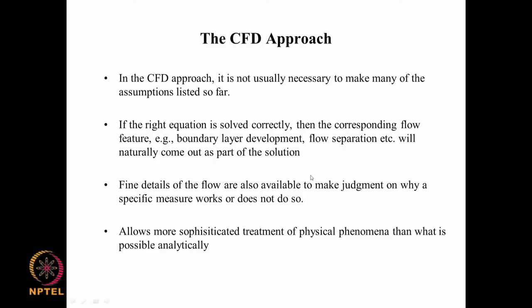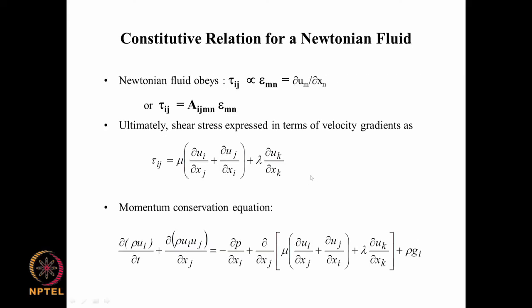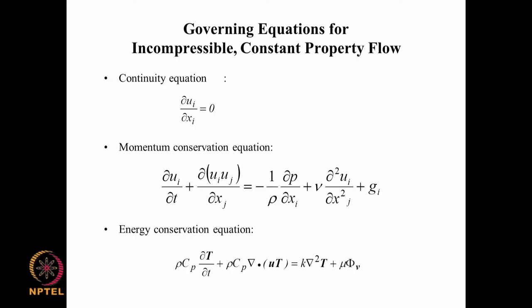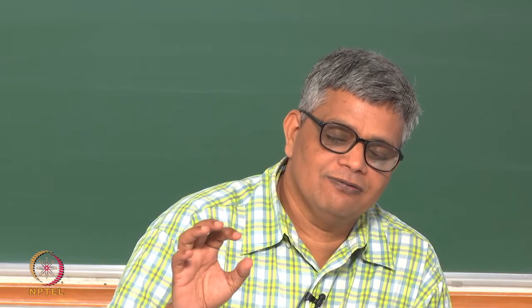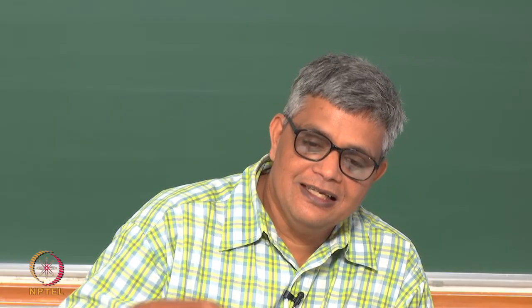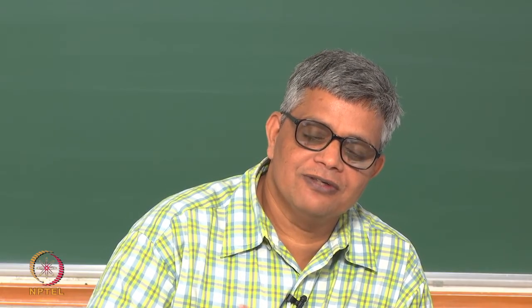In the general case, we have only the Navier-Stokes equations that are applicable, and these are the things that we try to solve, so that when we solve any CFD problem, we do not make any assumptions as to whether the flow is creeping flow, whether it is boundary layer type of flow or fully developed flow and all that. These things come in the specification of the flow domain and the boundary conditions, which we will see later on, and we specify those boundary conditions and we identify the flow domain.